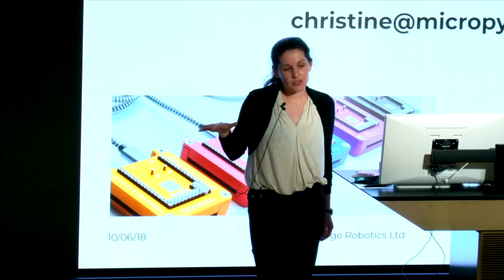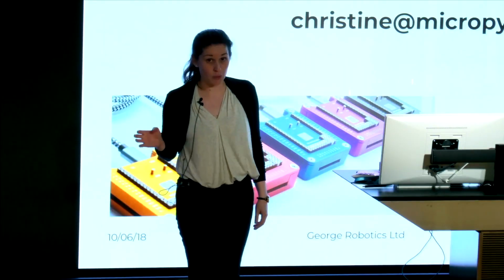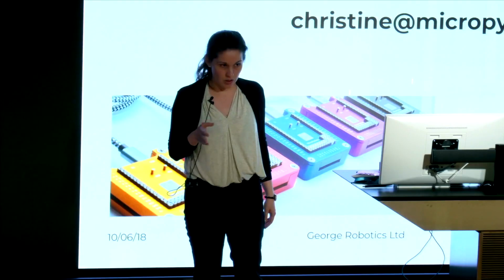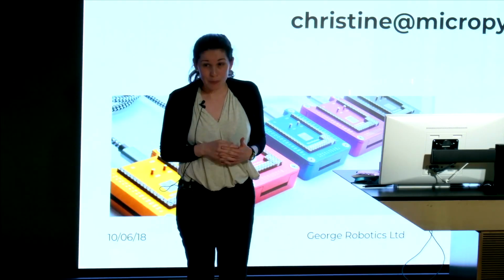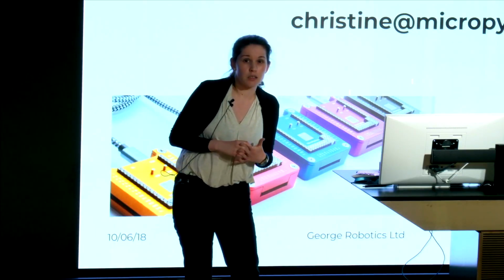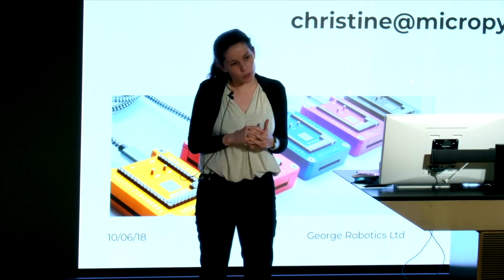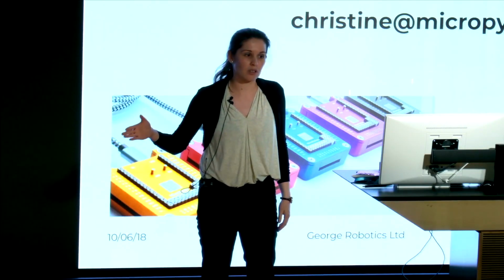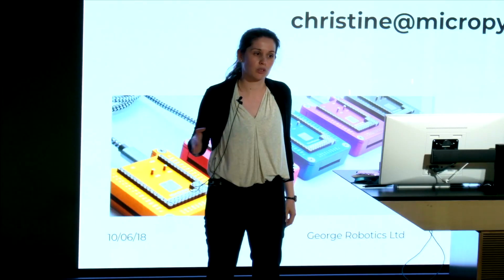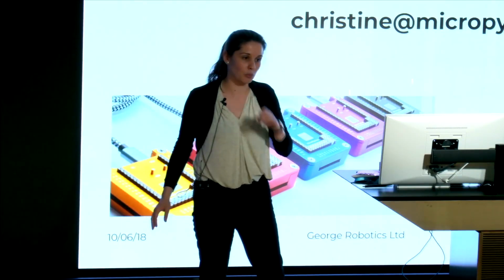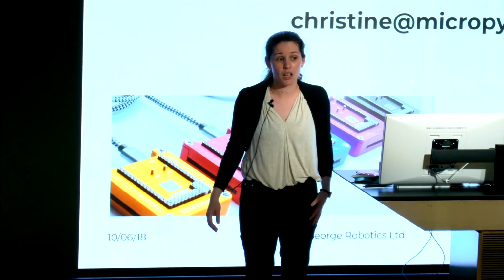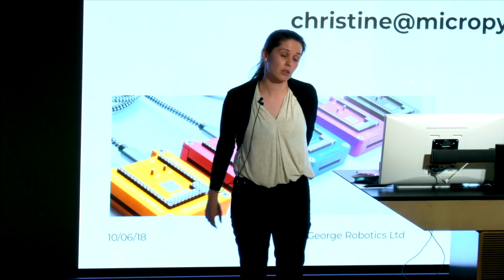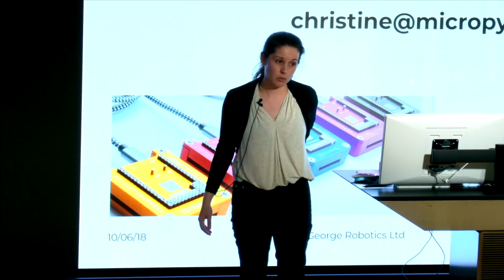Well, yes, you might have seen the official MicroPython has ports for the ESP8266 and ESP32. They are cool chips, but if you want to explore and don't want to spend a lot of money, go with them. But if you really want to put this in a real application, I would not recommend it right now. I'm not saying they won't be there at some point, but they still have too many hardware bugs. But if you want to explore, sure, they might be a good, cheap start.